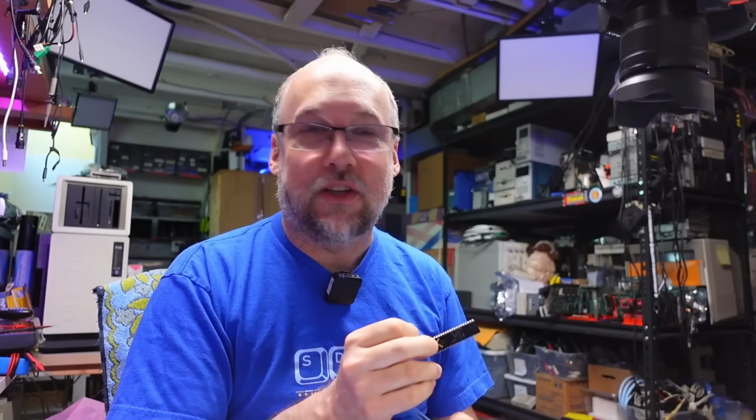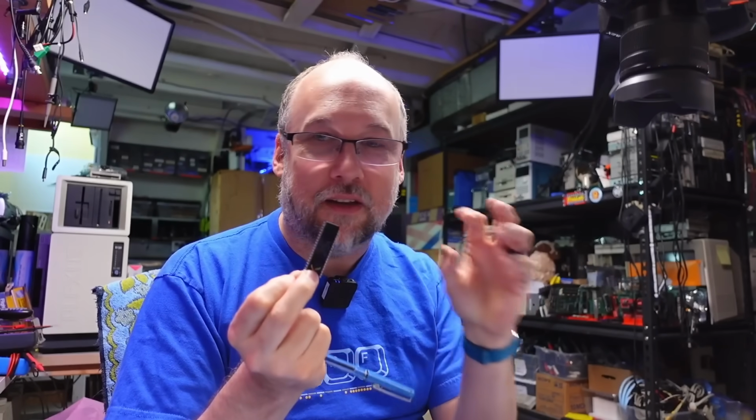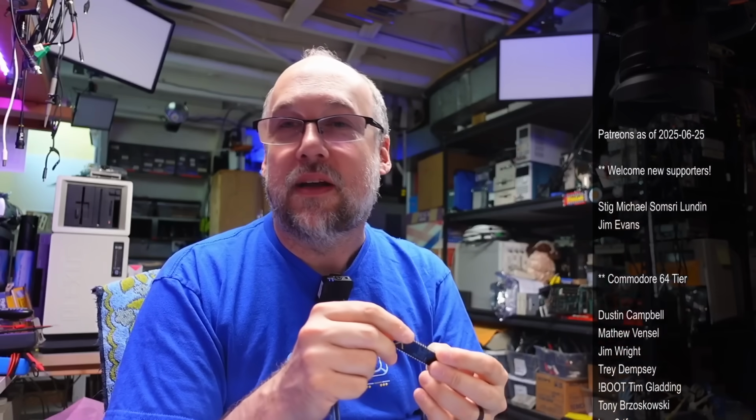But anyways, in the end, it was this bad video chip that was keeping this thing from booting, and it was really cool, and it was actually really fun to use that logic analyzer to see the commands that this was getting, the bad chip, and that it should have shown a video signal, and it wasn't. I really confirmed everything I think I knew, and it was awesome to confirm that by putting this chip in and having the machine come to life.